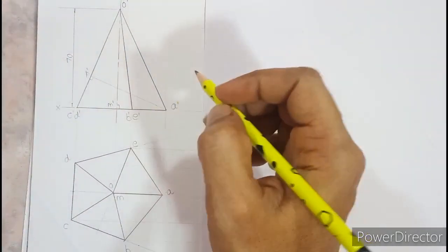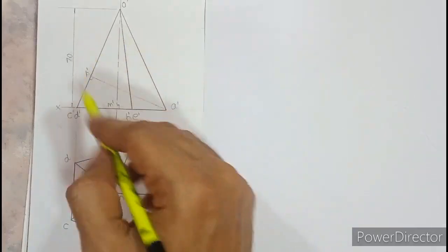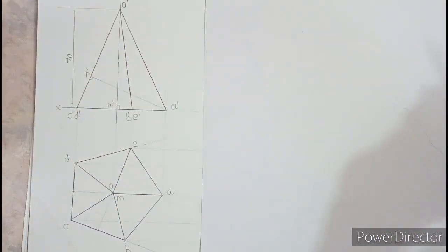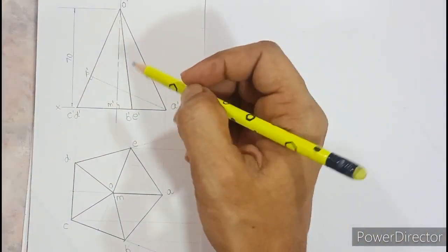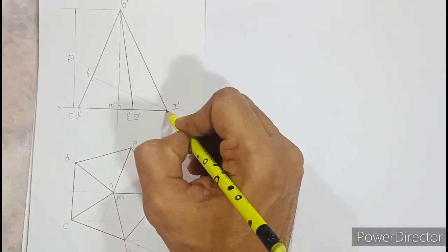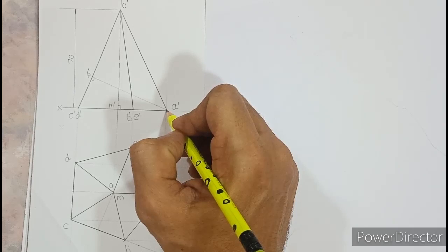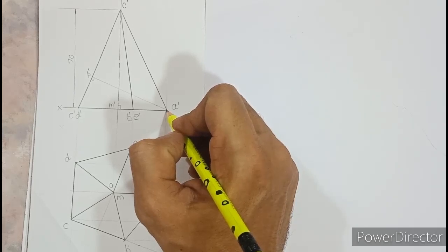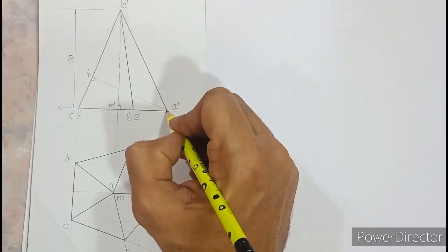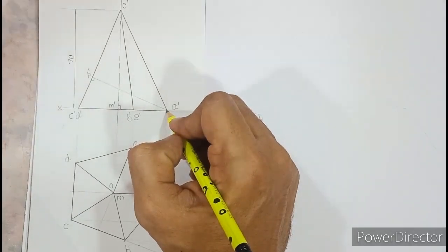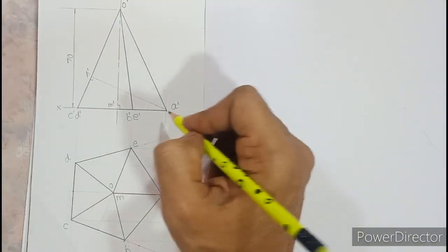So in the second stage, because the first stage condition is with HP, the second should also be with HP. We know that. So in the second stage, I want this corner A dash to remain on XY, because they said in the question, rest on HP such that something should rest on HP, either a base edge or a base corner. So we are making this base corner rest on HP, so corner A dash will rest on XY.